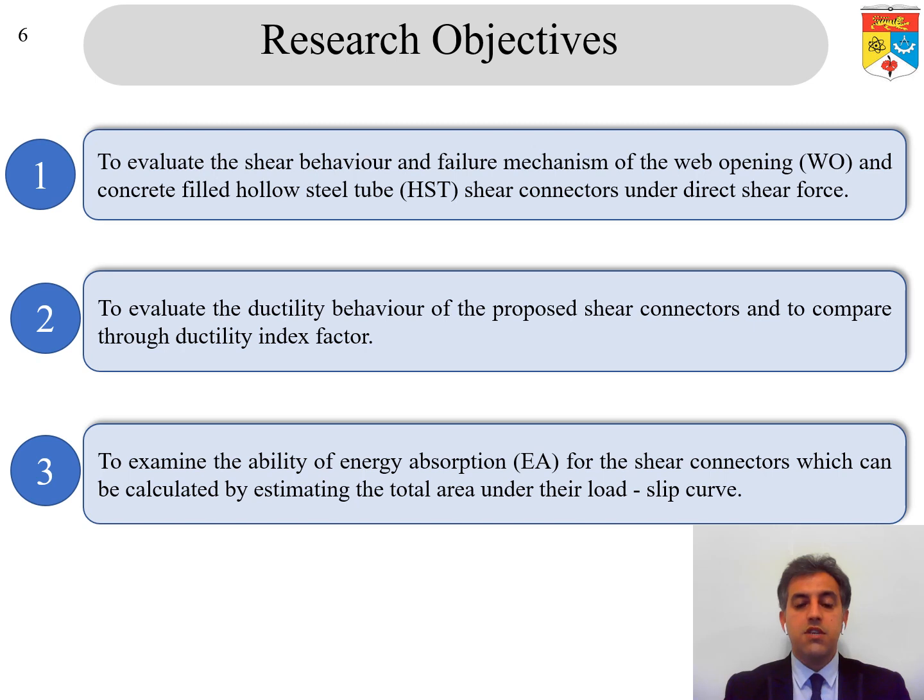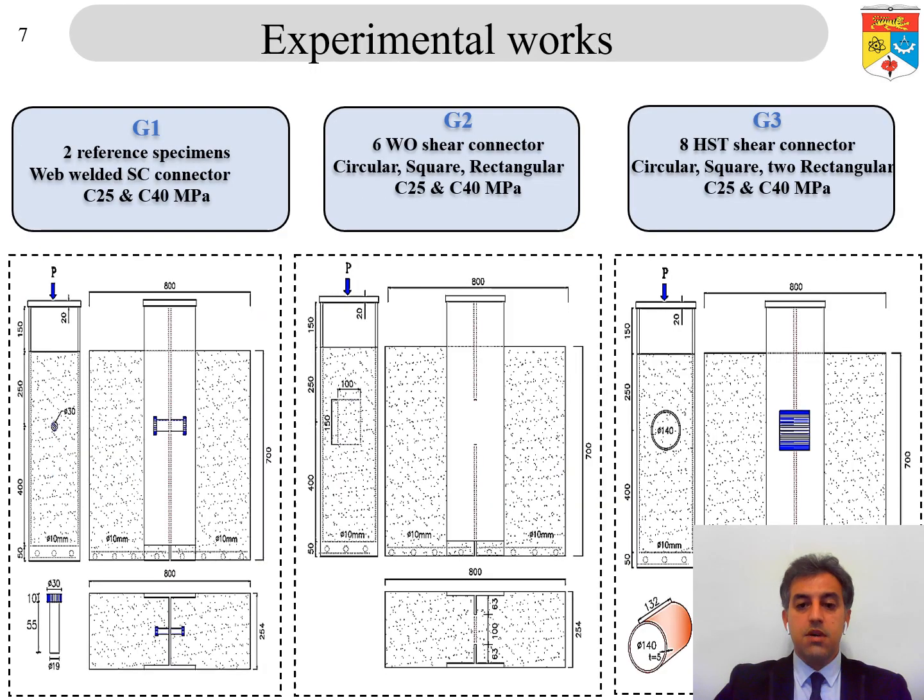So the objectives of this research are, first, to evaluate the behavior and failure mechanism of the web opening and hollow steel tube shear connectors under direct shear force. The second objective is to evaluate the ductility behavior of the proposed shear connectors and to compare it with other types of connectors through the ductility index factor. And the third objective is to examine the ability of energy absorption of the shear connectors, which can be calculated by estimating the total area under the load-slip curve.